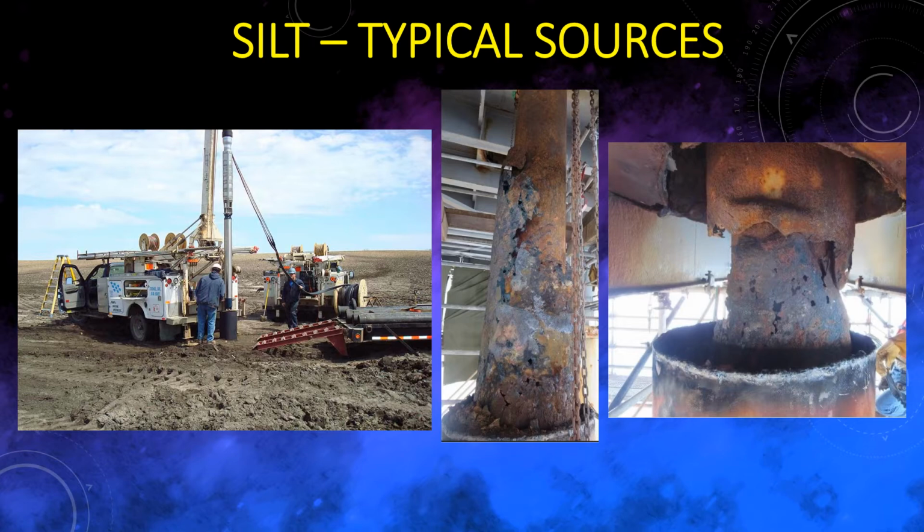Other issues, like in West Texas and other parts where we have declining well levels, as they drop the pump lower to accommodate that, you start pulling out of areas where they don't have it gravel packed right, or you start pulling from areas that allow silt and solids to come through and plague your irrigation system, mainly your filters.